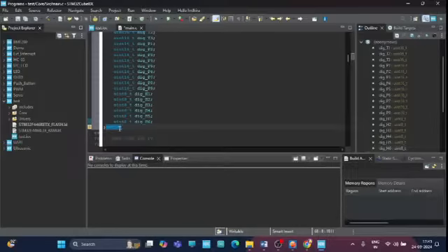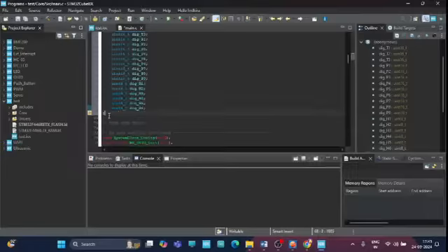After this, BME280_calib. This structure stores the calibration data needed to correctly interpret raw data from the BME280. Calibration values like dig_T1, dig_P1, dig_H1 are all coefficients that the sensor provides.